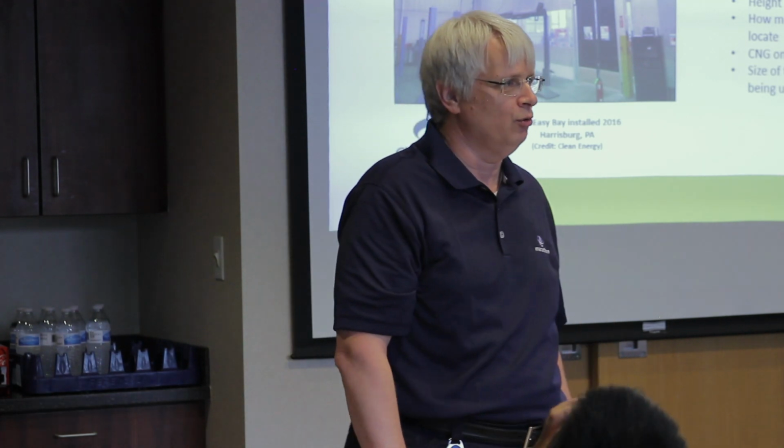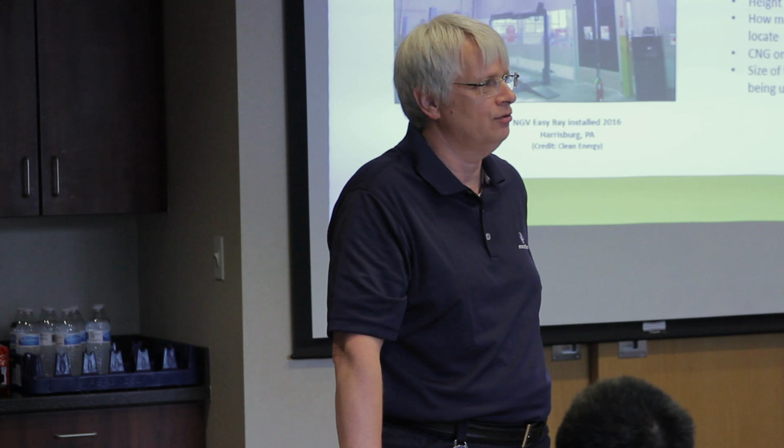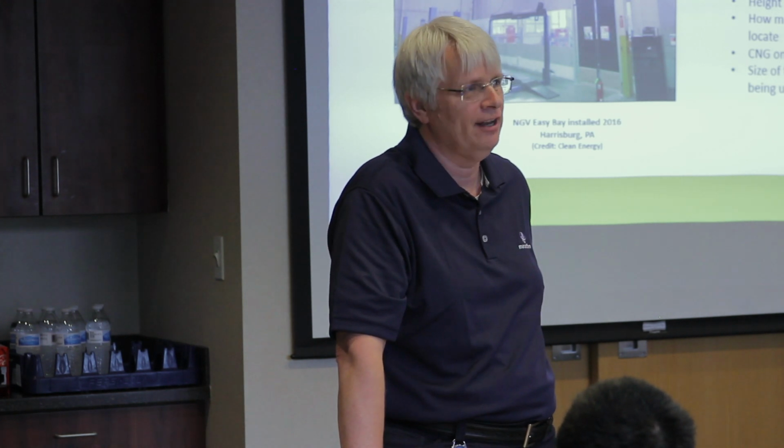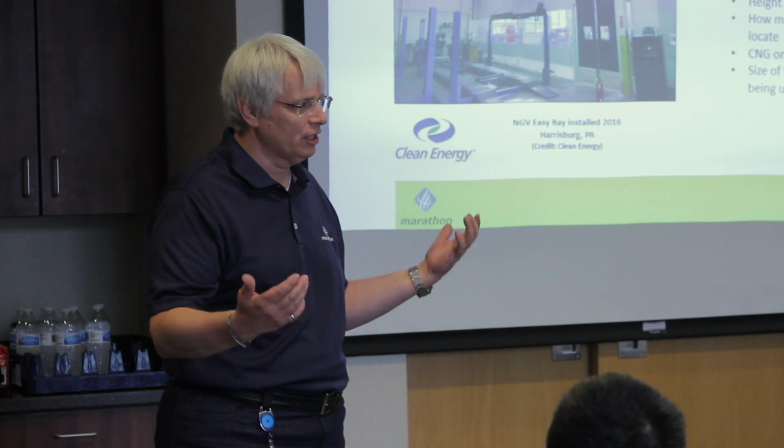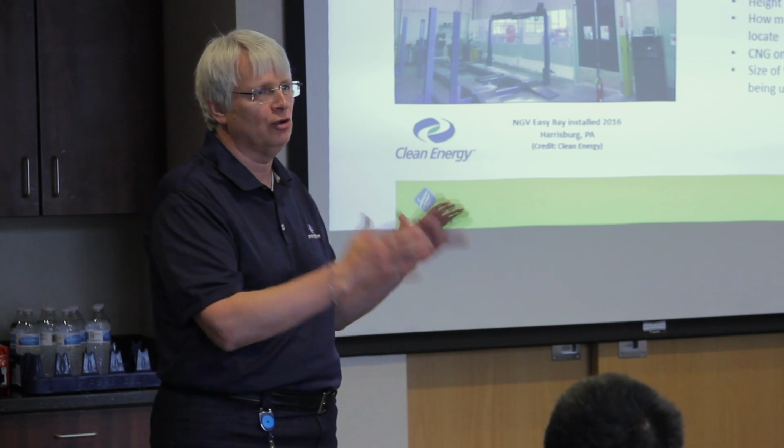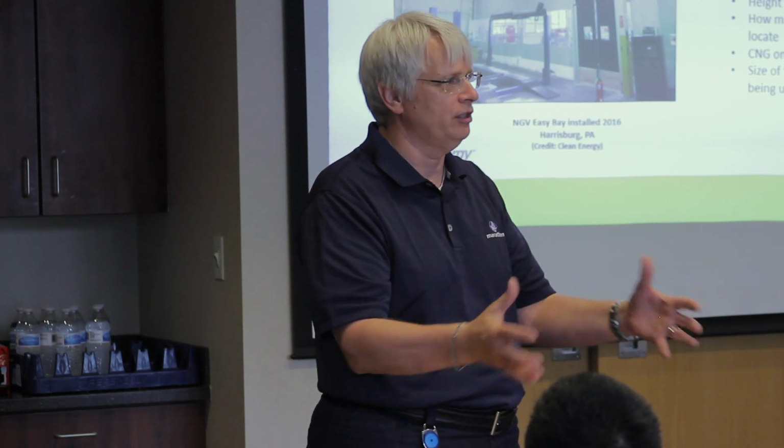So they had proposed to build essentially a bomb shelter around one bay with heavily reinforced walls and blast panels and everything explosion-proof inside, way beyond what the code would require. And actually they were referencing codes that had nothing to do with CNG. They were the kind of codes that you folks might use in your facilities. They were really intended for an industrial gas or refinery type of application. So that was the all-in approach, and their idea was, well, we'll make this one space really safe.